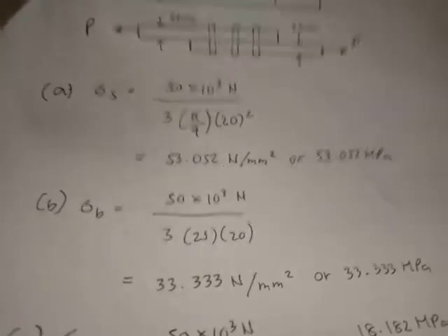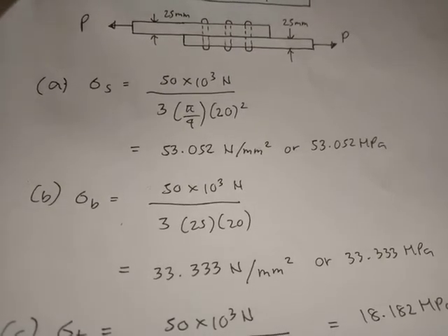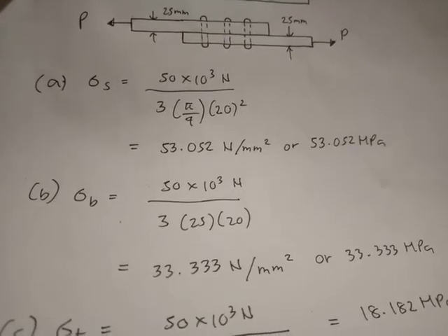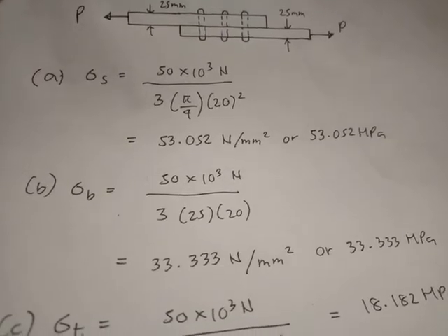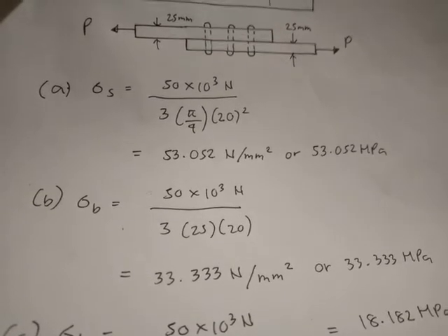So we divide, and we get the answer for the bearing stress, which is 33.33 Newton per mm squared, or we can say it is 33.33 megapascals.